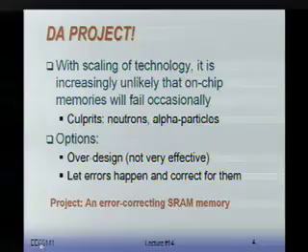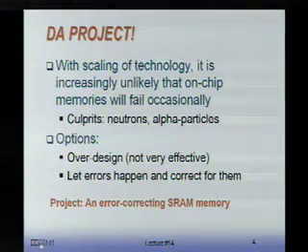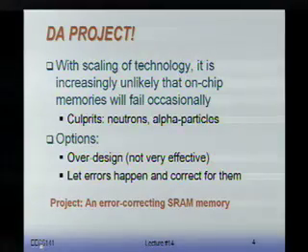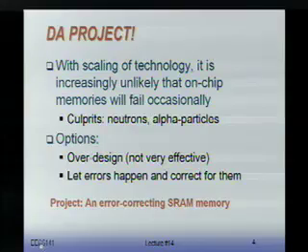If you buy a 1 gigabyte disk today, don't believe that all the bits on that disk are working. They do a test and exclude certain sections of the disk which are not working. We can do this on chips as well with memories. You take some rows, some columns, you say, there's an error in there, I'm going to exclude that. So manufacturing errors are something we can deal with.